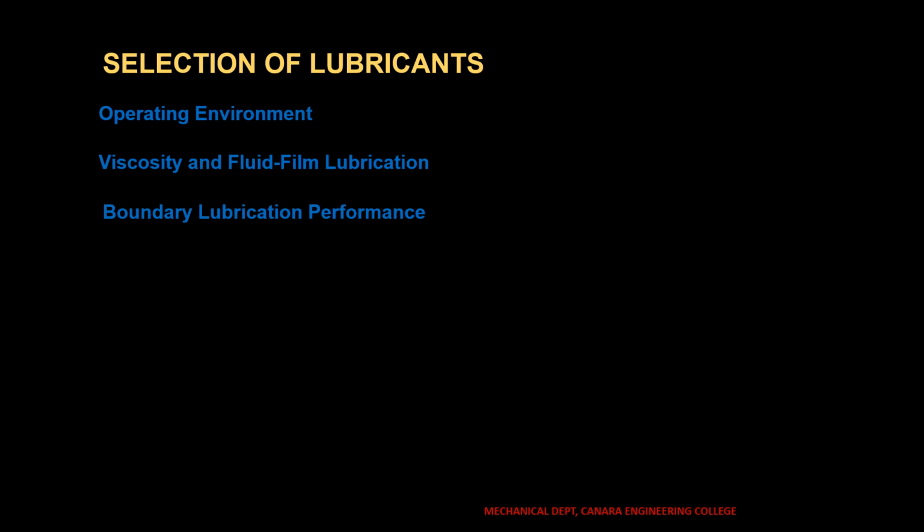The surface films thus formed are generally low friction and wear resistant, and protect the surfaces from early failure or wear. Anti-wear or lubricity additives are generally added to the base oil to enhance the formation of protective surface films during boundary lubrication.